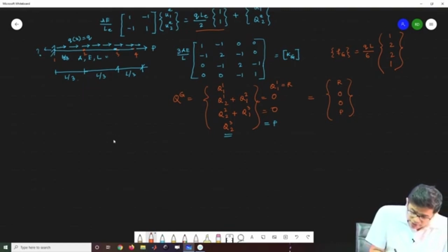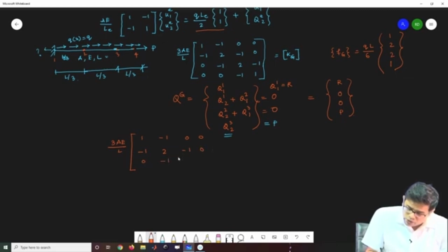Now if I write it, then my 3A by L times the matrix [1 -1 0 0; -1 2 -1 0; 0 -1 2 -1; 0 0 -1 1] multiplied by U1 U2 U3 U4, because I have 4 degrees of freedom.